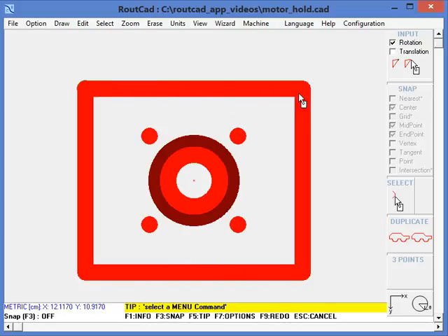Anything in red or other color is the material that was removed by the CNC milling tool. So we can see these 4 holes that we have done to put the fastener for the motor mount, and we can also see the bore, the full bore that was made, and the countersink.